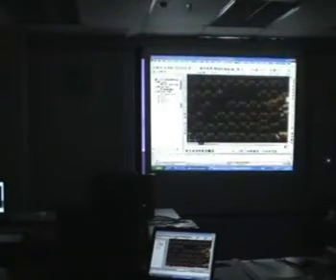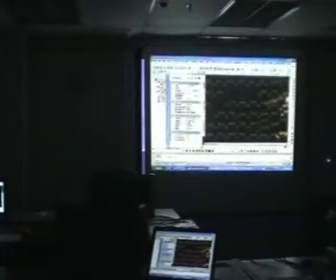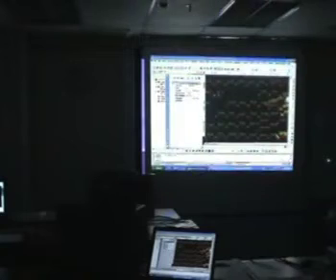Now, each of these objects is a unique object called a point object. This does not exist in AutoCAD, because in AutoCAD you have points, you have text, you have blocks. This is very unique in the sense that it's a civil point object. Let's say, for example, I just select this object. We can look in the properties window. Say this is a civil point object. That means it recognizes this point is not just a normal point. It's actually a point on a surface which we can use for triangulation.